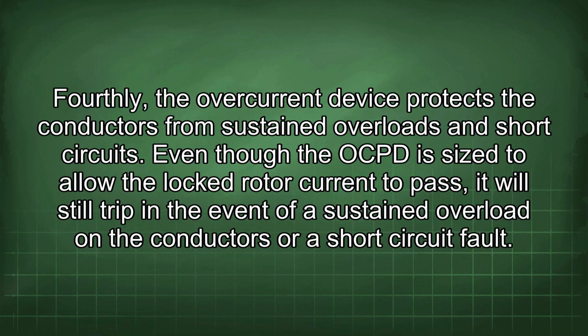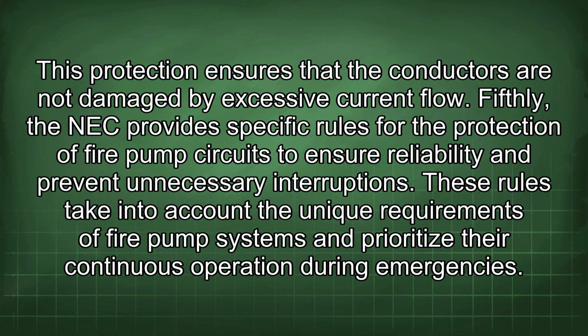Fourthly, the overcurrent device protects the conductors from sustained overloads and short circuits. Even though the OCPD is sized to allow the locked rotor current to pass, it will still trip in the event of a sustained overload in the conductors or a short circuit fault. This protection ensures that the conductors are not damaged by excessive current flow.